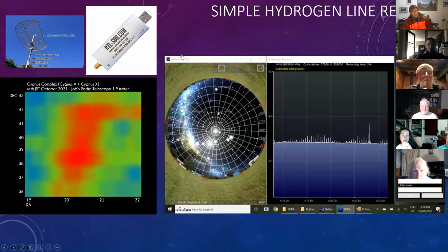the dish is creating an upward-looking view of the sky to the receiver, and that's just got a little bit of cable, and it's got the USB dongle just below the dish, so that the actual RF feeder connects to the active element, which is that little blob at the top, and it's actually called a dipole, which sits above the dish. That's where the dish bounces the signal to. So it receives all of that energy from around the sky and focuses on that, very much like a parabolic dish in a mirror, for example.